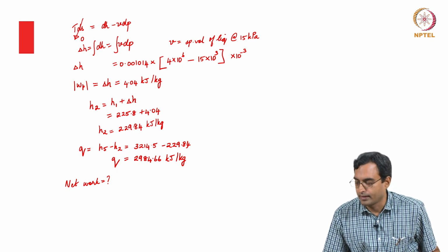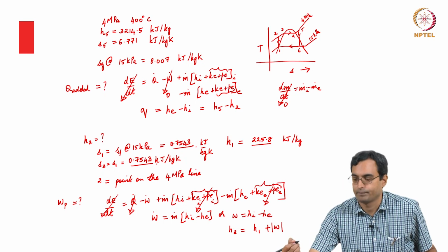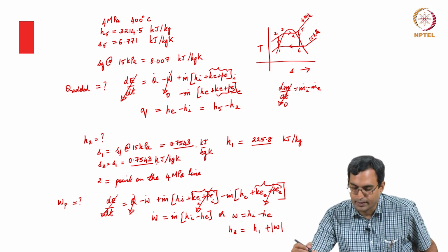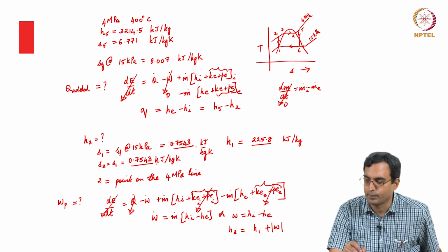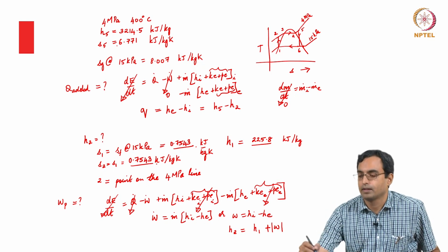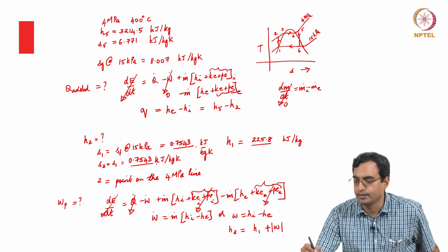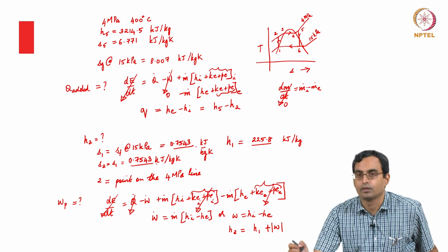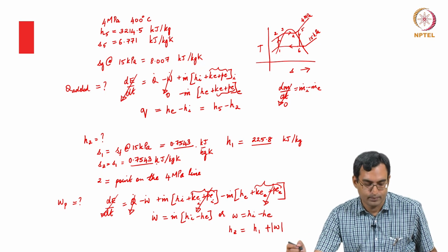Now, if this was an ideal process, we would go from 5 to this 0.6. So, we can find out what would be the work in the ideal process. For the ideal process, we know the inlet condition, which is enthalpy at 5, we know the entropy at 5. For the ideal process, this 0.6 lies on this 15 kilopascal line. It has the same entropy as the initial. So, we can use that information to find out what is the quality at 0.6.